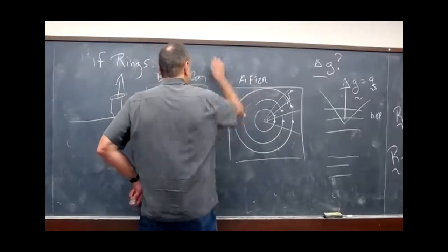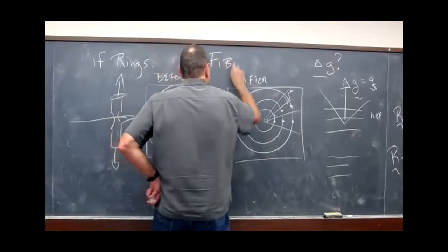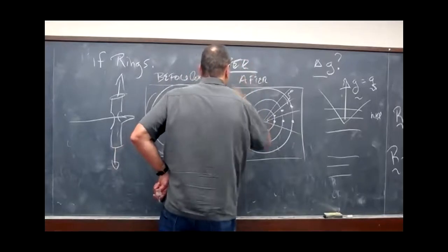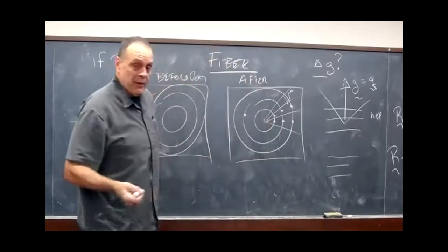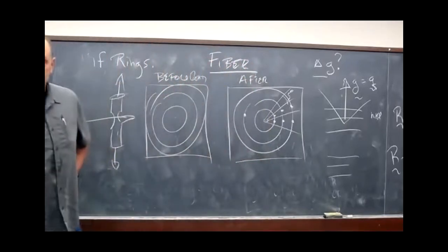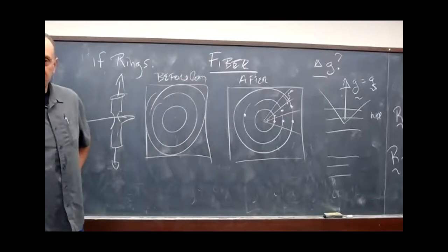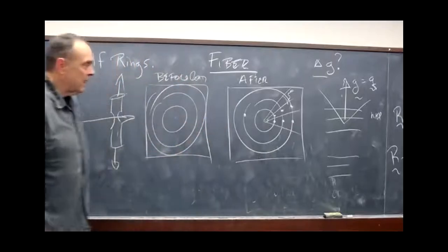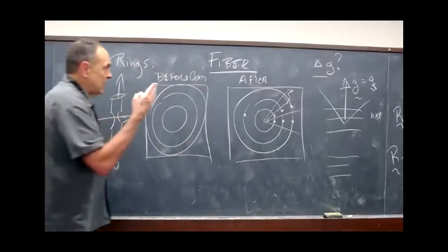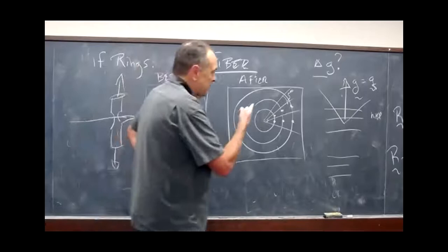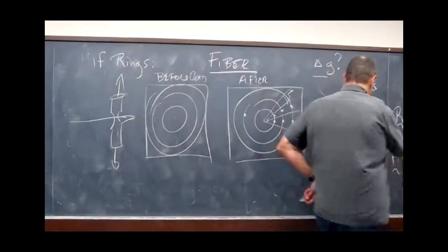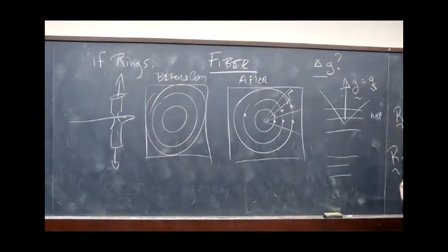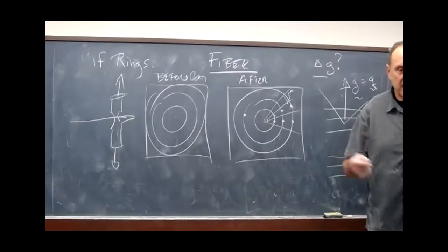So that spot lies along what's called a fiber, a fiber in orientation space. The cool thing about a Rodrigues parameterization is that a fiber looks like a fiber. It's just a line, and so it's great. So anyhow, that strain is now associated with all these crystals that lie along this fiber. So the question of what you do with that is what we're going to talk about now.